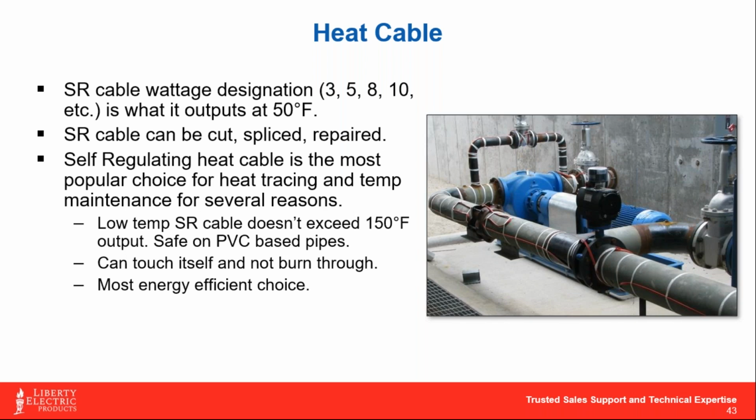So when we talk about self-regulating cable, it gets its name because this cable is able to expand and contract based off the surface temperature of what it's up against. And that's how it throttles its heat output up. So there's a standard within the industry, and when we designate a heat cable as, say, a 3.5 or 10 watt a foot cable, that's what that cable's emitting at 50 degrees F. And the colder it gets, the higher that wattage value is going to be. And the warmer it gets, it really doesn't cut back much below what the rated duty is, and that's just due to the construction of how these cables are made.